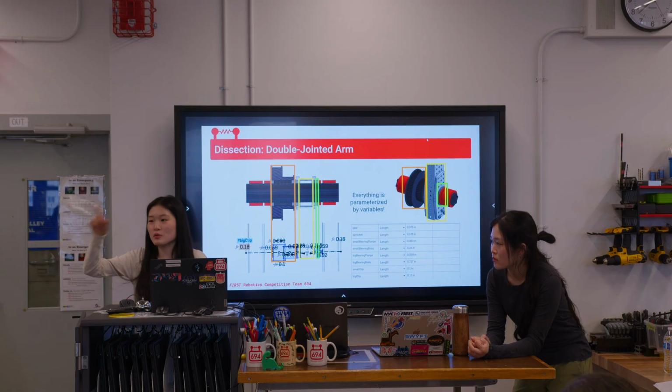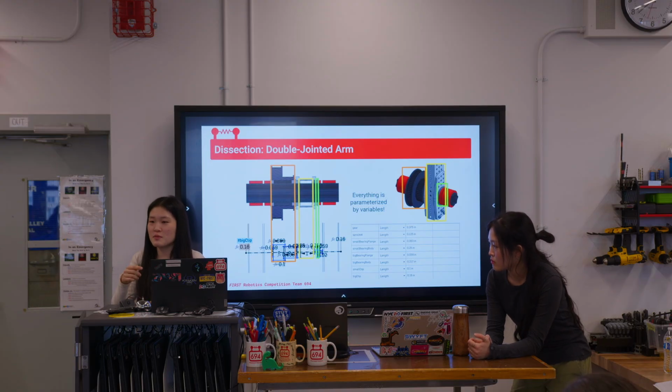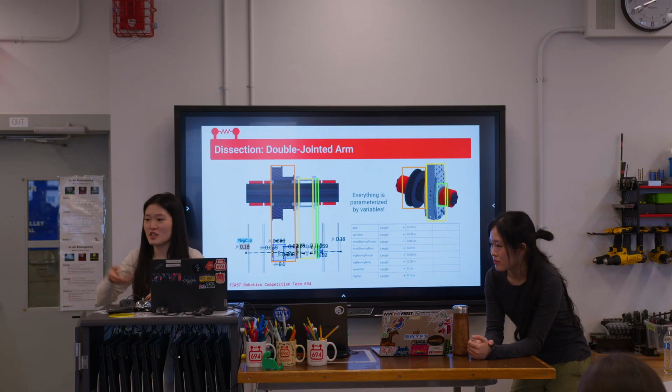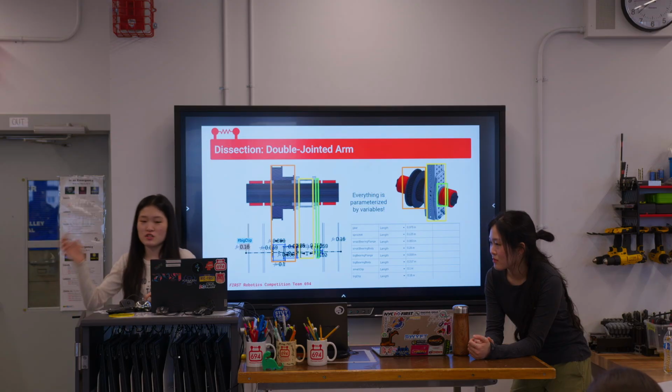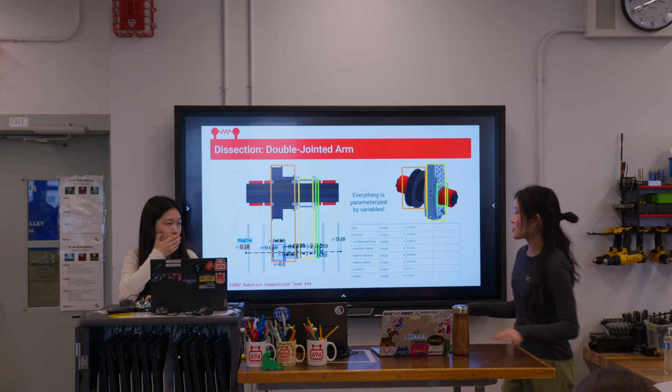I don't draw the belt path because I want to do that in the mechanism document. I'll just make it 500 millimeters, a perfect distance. But I'll also decide that during prototyping, because if you don't want to use a belt tensioner, during prototyping I'll immediately decide I want to use a good number divisible by 5 millimeters, and then test that out. If that works, I'll just define that on the robot mechanism.